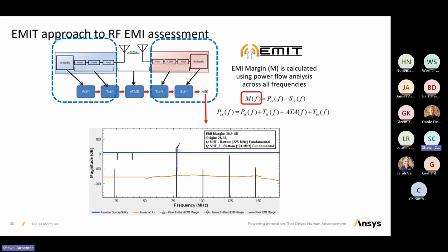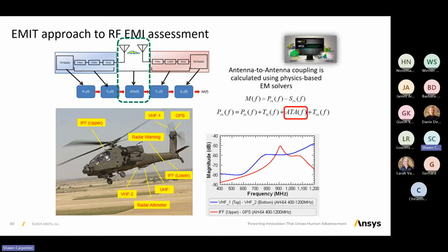And then what we do is take that ratio all the way through to the end so that you can overlay across the entire band to understand what kind of a problem do I have? Is it an in-channel problem, an out-of-channel problem? Where are the transmitters involved in this tuned when the problem occurs? Because it's looking at all the channel combinations to help me understand where I will have problems with any channel set.